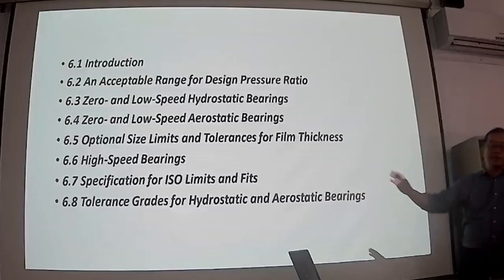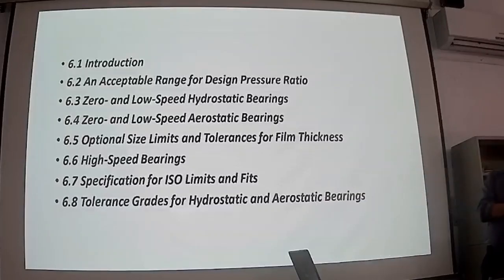However, sometimes you send your technical drawing to the factory to manufacture your hydrostatic bearing, and the control of the tolerance is not so good, so your film gap thickness is bigger than your original design film thickness.